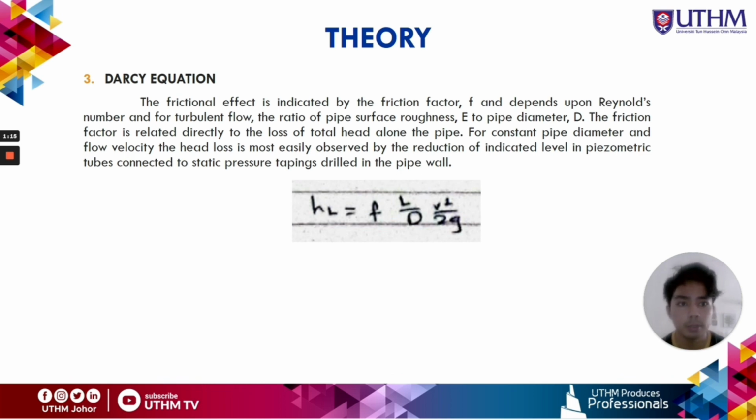For constant pipe diameter and flow velocity, the head loss is most easily observed by the reduction of indicated level in piezometric tubes connected to static pressure tappings drilled in the pipe bore.